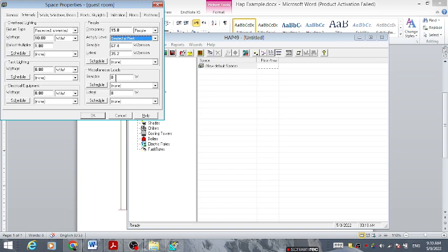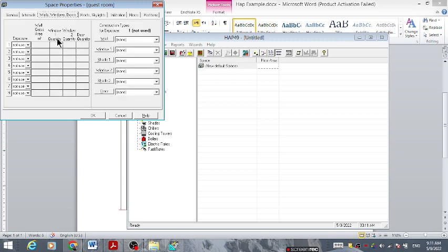Do you have any miscellaneous loads like printers, computers, kitchen equipment? Any of these you can add here. How many watts of heat? Be careful, this watt is for heat generation, not electricity. Rate of watt. Okay, the other window is walls, windows, doors, so we need to add them.